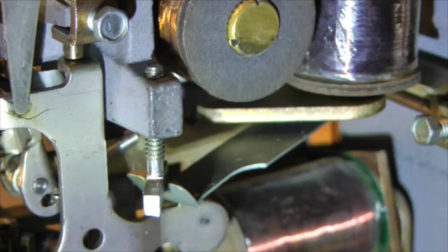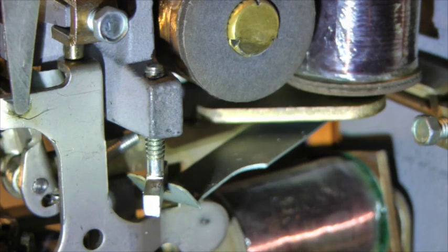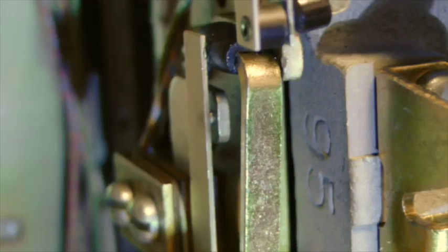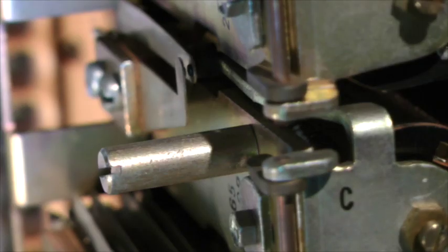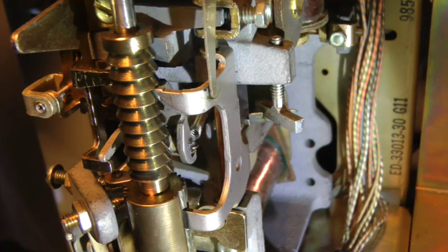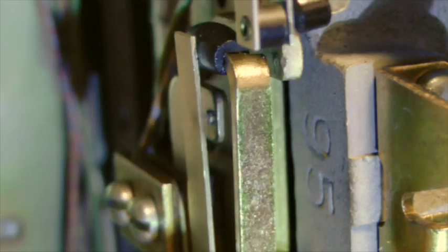What you are looking at is a line finder switch. It is one of 3 main types of switches used in step-by-step telephone switching systems, the other 2 being the selector and the connector. The main purpose of the line finder is to hunt for a telephone line that has gone off hook in an attempt to originate a call, and then to connect that line to the dial switch string so that dialing the called number can begin.